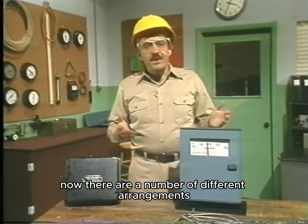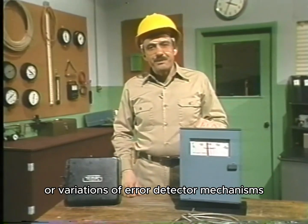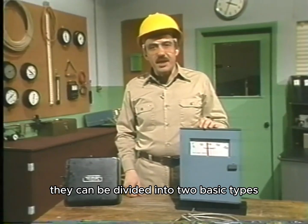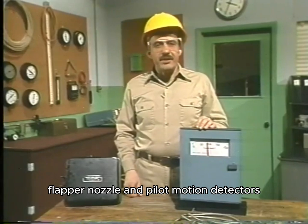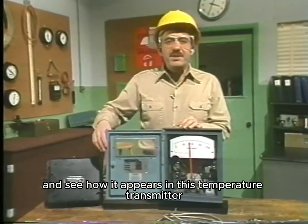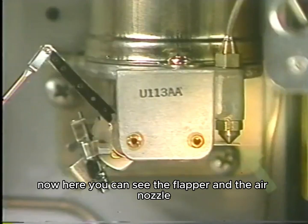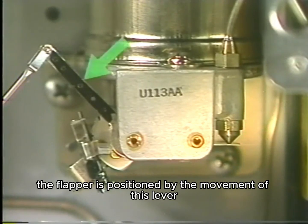Now, there are a number of different arrangements or variations of error detector mechanisms. However, generally speaking, they can be divided into two basic types: flapper nozzle and pilot motion detectors. Let's look at a flapper nozzle arrangement first and see how it appears in this temperature transmitter. Here you can see the flapper and the air nozzle. The flapper is positioned by the movement of this lever.